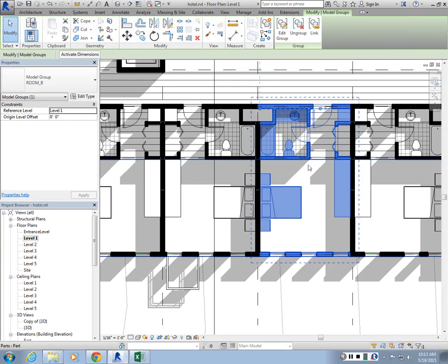I didn't include the floors because I'm going to show you next. The floors are made through parts so that you can create different types of hatches for the graphic representation. And when you try to include them in groups, it doesn't work. So you can only copy slabs, but when you want to include patterns as well, you want to keep them separate.